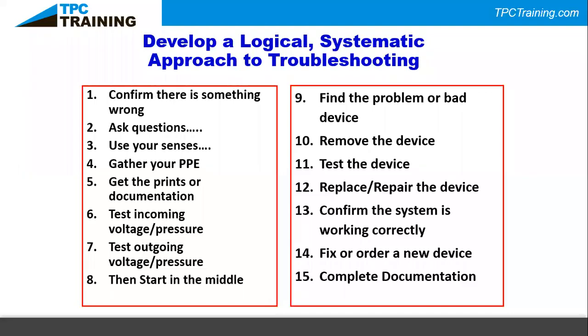So it's really important to try to get a narrow list of things that could be wrong. And then when you're in the panel, now you have a really quick action plan. Okay, one of our things on the list was that we don't have power to the panel. Well, boom, I can verify that now. From going from line 1 to neutral, I can verify whether that's true or not. Okay, cross that off the list. Now, during our brainstorming session, we also said that the wiring going to the motor starter could be bad. And then I'm going to start testing that, so on and so forth.